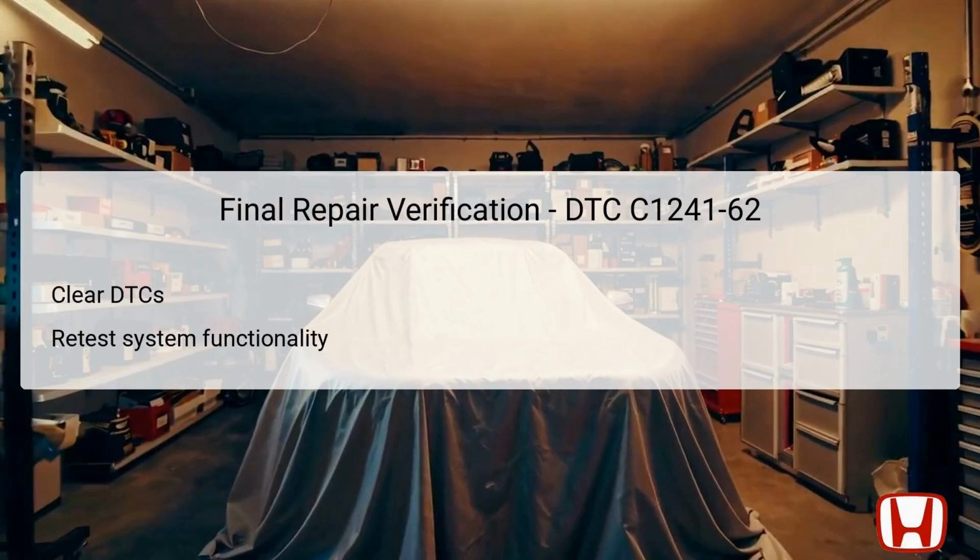Once issues have been identified and repairs have been completed, it is crucial to proceed with final repair verification. First, clear any diagnostic trouble codes, DTCs, from the electric vacuum pump system using the HDS. This action resets the system and allows for re-evaluation without the prior error codes interfering.